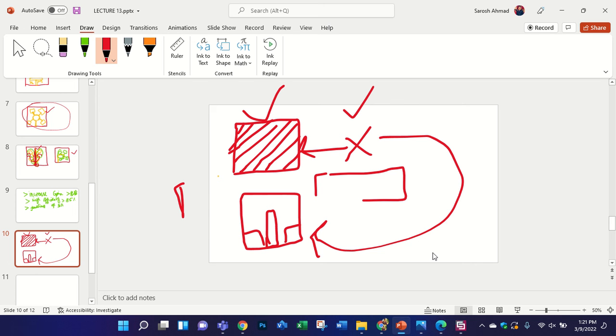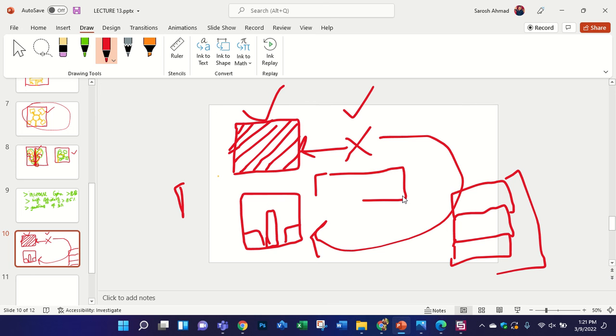Yes, for the superstrate, I am still talking about the thickness. Suppose this is your antenna array, and surely the metamaterial sometimes does not work very close to the antenna, so you need to take some foam of 5 millimeter, and then place your metamaterial, and you see that it will become a thick profile, so it cannot be called low profile. Maybe we are afraid that if you use the metamaterial, we will have the same gain as using the complete ground or the full ground.